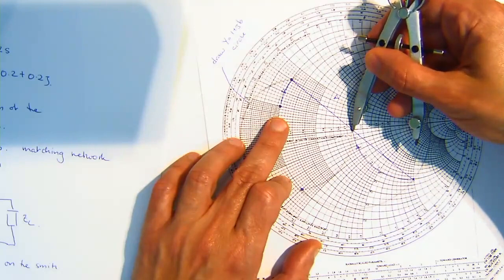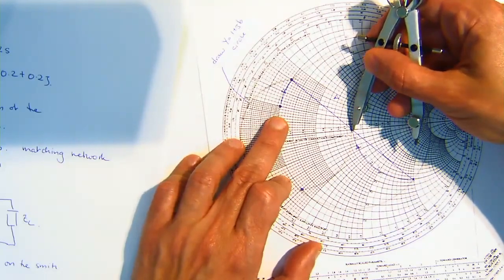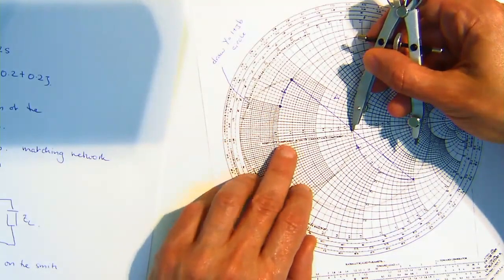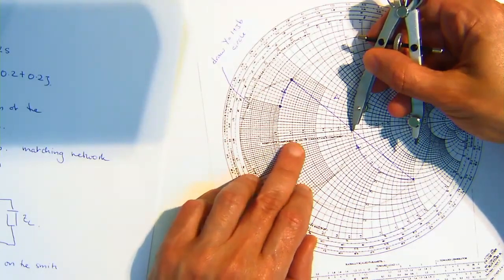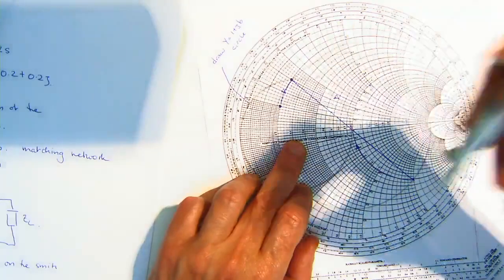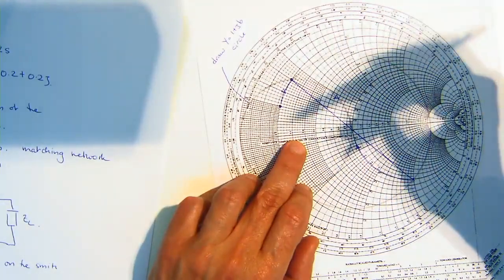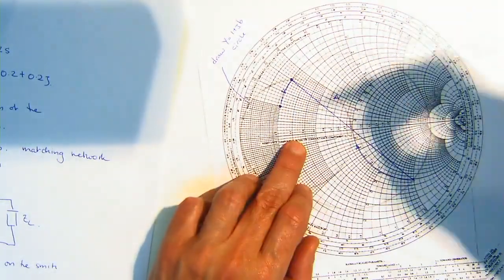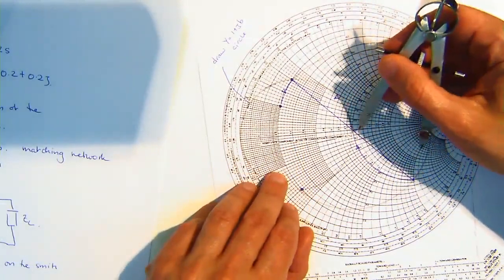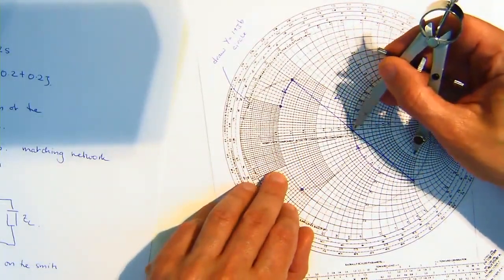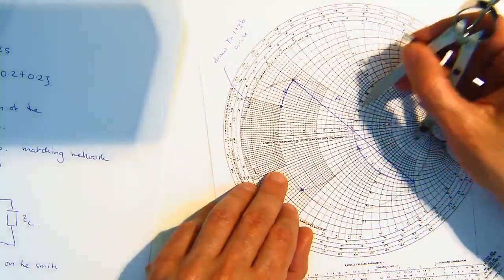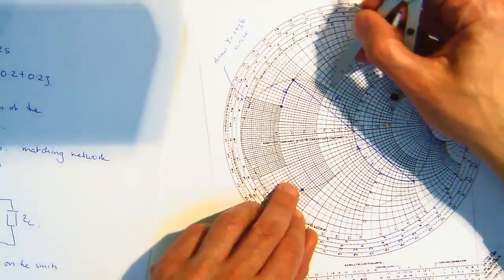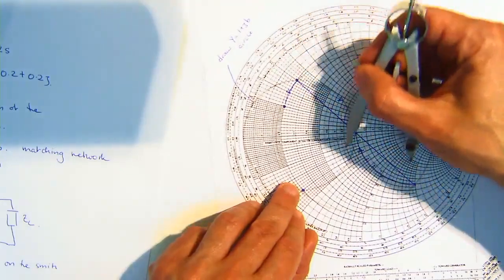And the best way of being able to do that, or the only way, is to draw the voltage standing wave ratio curve for 1 plus jβ, which is the unit susceptance circle. Rather than going here where you've got Z equals 1 plus jβ, I'm asking you to draw the line Y equals 1 plus jβ.